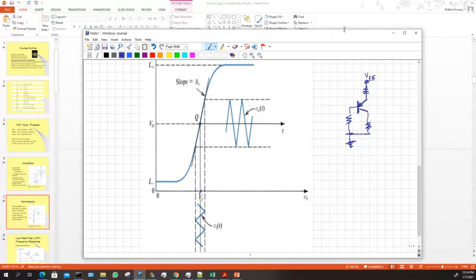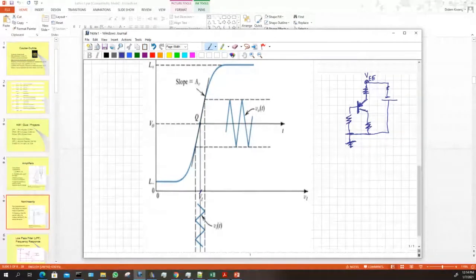I just draw VE here, and I assume, what do I assume is here? I assume here that there's a battery. Okay, so it's going to be a positive voltage. So it's going to go like this. I assume that there's this nice battery, and it provides me exactly the right amount of voltage here. But I can't guarantee that. That has an internal resistance and leakage, whatever. Like, it's got nonlinearity. So I put a little resistor here, which is higher than the internal resistance of whatever VE is, so that my calculations will come out according to my resistor rather than the resistor of the system, right? So usually you have resistors.